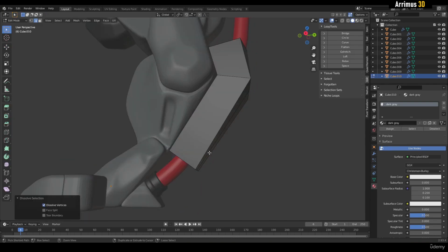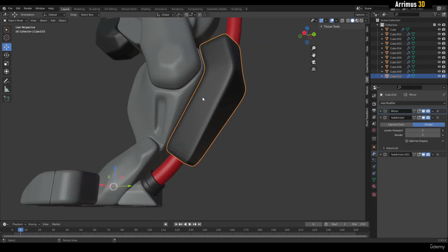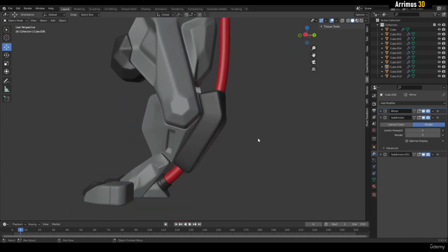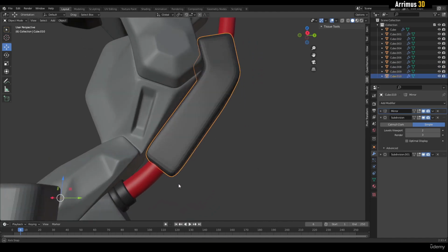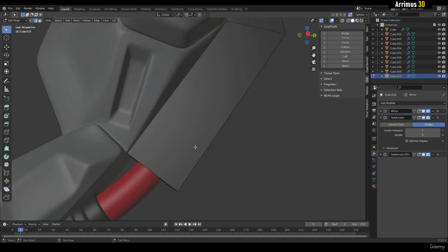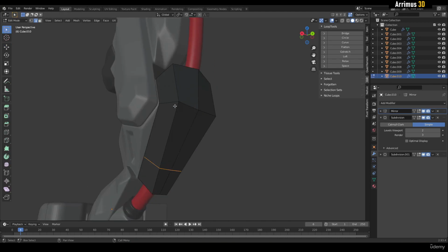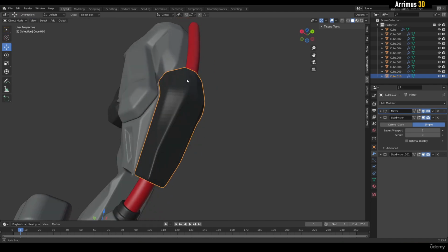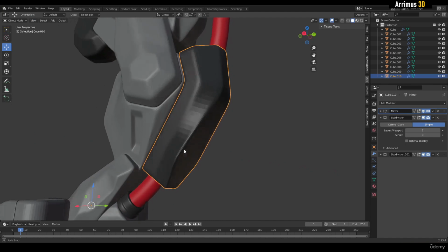And sometimes you can actually insert a loop just to sharpen things up. Like right here, I think it's way too. Actually, we can go back to using 2 for now. All right. So if you think this is kind of awkward, you can always go in here and add a basic loop here just to sharpen things up. And this just opens up a lot of nice possibilities for you.